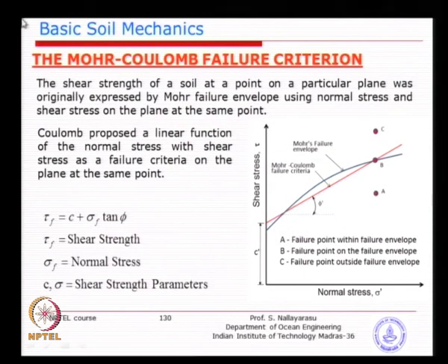So, one of the parameters we see here is the undrained shear strength, or shear strength as you call it, and the angle of internal friction. This is a typical C-phi soil, which comprises sandy clay or clayey sand with several fractions.